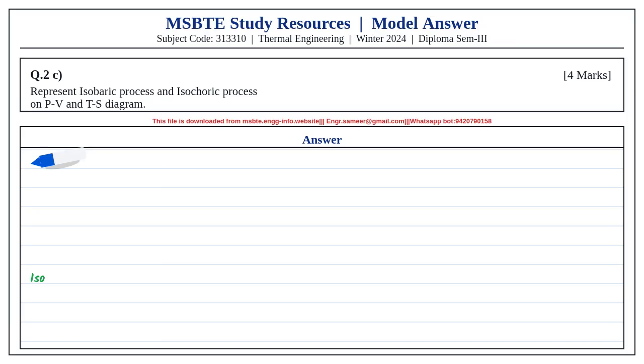0.1176 kg. Since volume remains constant, pressure divided by temperature remains constant. Therefore T2 is equal to P2 by P1 multiplied by T1. Substituting values, T2 is 924 Kelvin or 651 degrees Celsius.